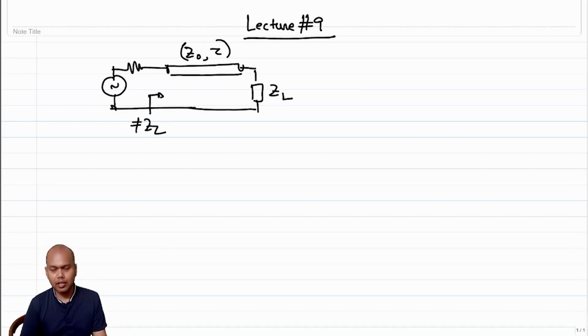The other problem is, if we, let's say, try to find out the impedance of an open circuited line, I might end up interpreting it to be a short circuit depending upon the length of the line. And similarly, if one side is short circuited, I might end up interpreting it like an open circuit, depending again on the length of the line.